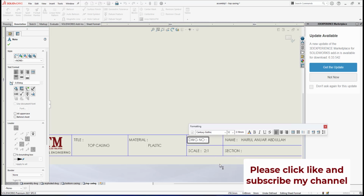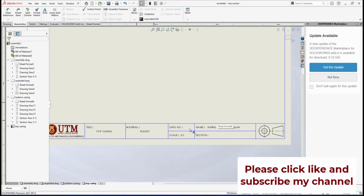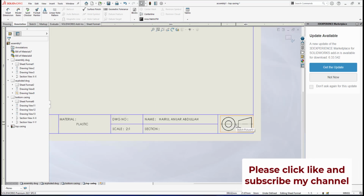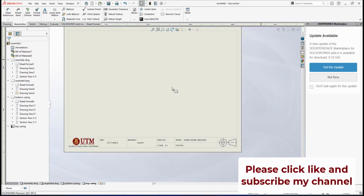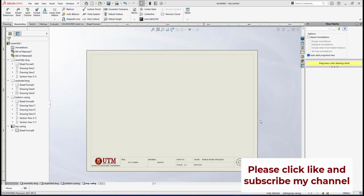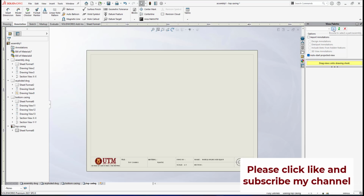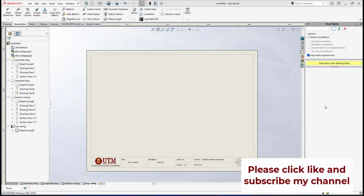Okay, for the top casing, the scale also will be 2:1. Make sure your title block is completed and the top casing detail drawing is orthographic, so we must have the third angle symbol. Now I will exit the edit sheet format. Alright, for this top casing detail drawing, under the view palette, as you can see here, I have nothing here since I have not browsed the top casing file, so I will browse it. I go for top casing and click open.